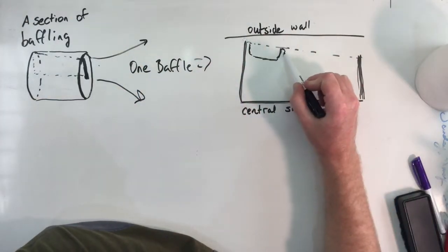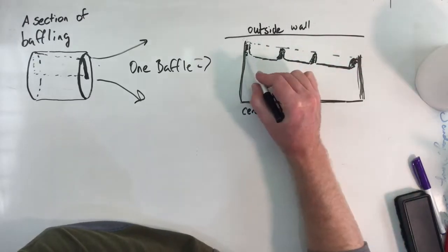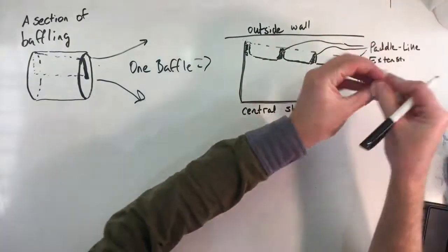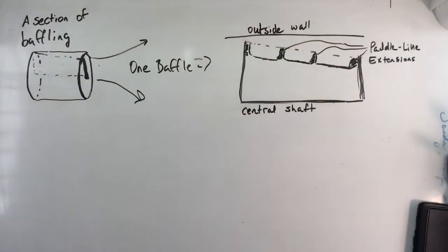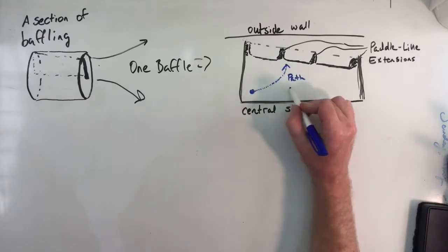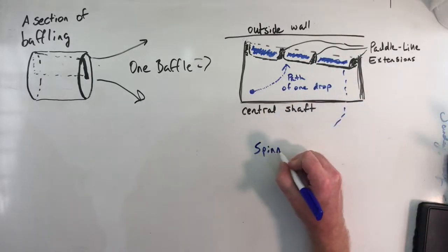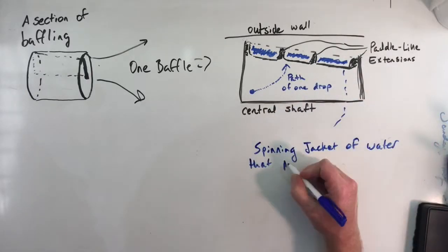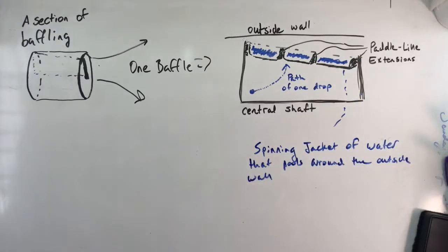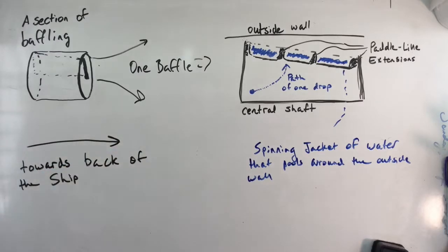Now let's say that a drop of water forms from the steam that condenses on the baffle surface. It is accelerated towards the back of the craft as it resists the acceleration of the ship forward, and is accelerated away from the axis of rotation on the baffle as it resists the centripetal force from the baffle surface. In the end, it moves diagonally away from the axis of rotation from our point of view. As it travels further from the axis of rotation, its path will also curve as the amount of centripetal force that it is experiencing increases.